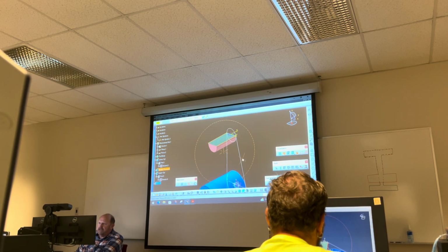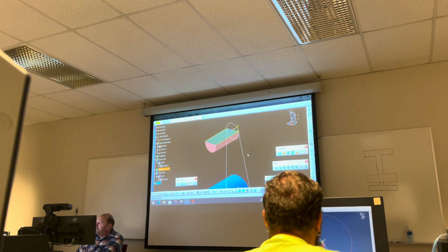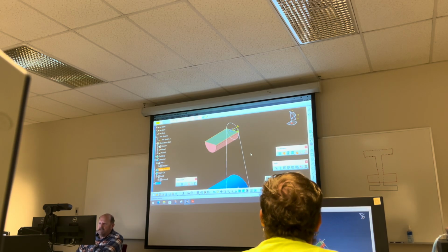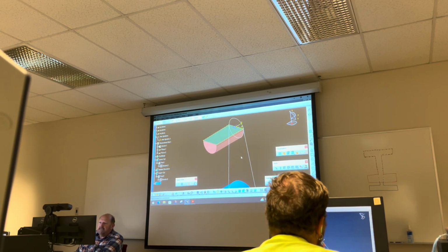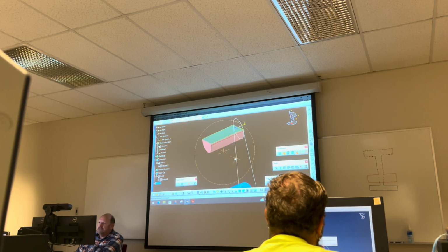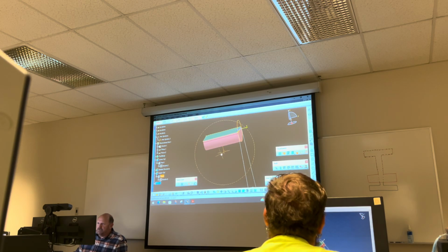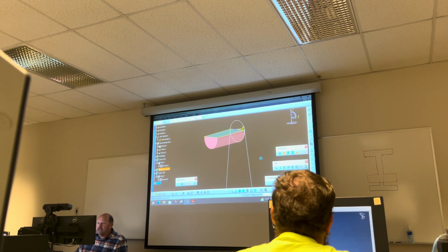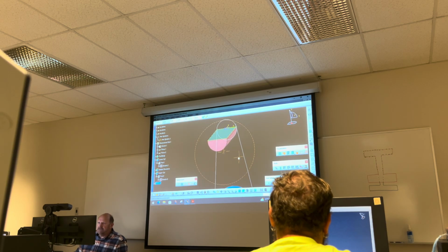The reason it gives you that is because you're on something that is a cylinder. Doesn't mean it's not going to be right. But I needed those, and I also need the front and back of this. So I'm going to hit Control, pick this one, say insert operation 3D geometry, intersect 3D elements. Say OK. There's the front and back.